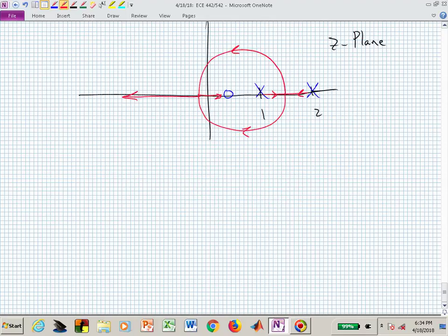But now here's a different philosophy. Instead of picking beta and then sort of anticipating where your branches are, which you kind of know quite a bit because of this 2 poles and a 0 structure, what if somebody said, can I pick closed loop pole locations, can I pick triangles, and then figure out if beta can be adjusted to make my root locus go through those triangles? Do you understand that thought process? Now locate your triangles and see if a beta exists to make that happen.